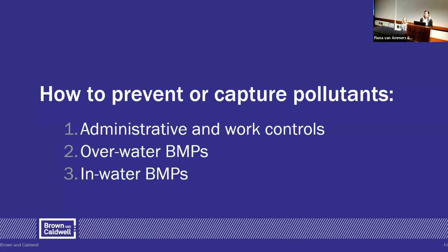Thanks, Fiona. Now I'm going to go over some steps that we can take to prevent or capture those pollutants from entering the waters and prevent them from muddying up our streams, rivers, and oceans. The first I'm going to go over are administrative and work controls, which occur prior to the start of construction. Next, we'll go over water or on-land best management practices, also known as BMPs. And last, we'll go over in-water BMPs themselves.